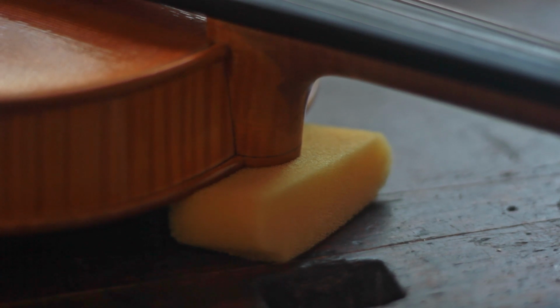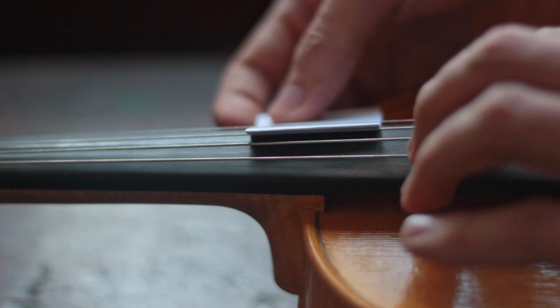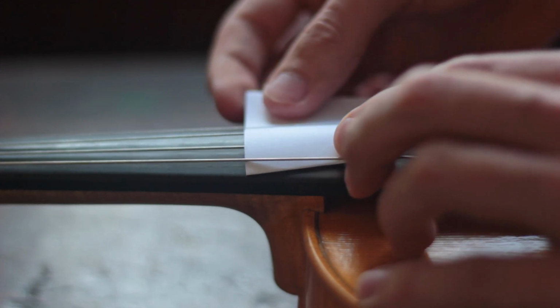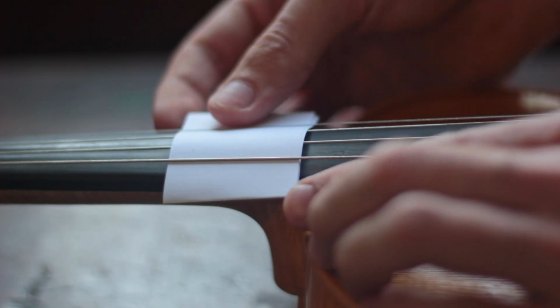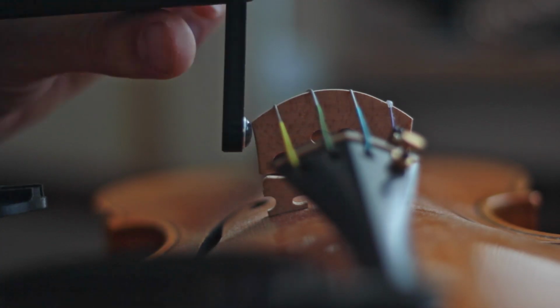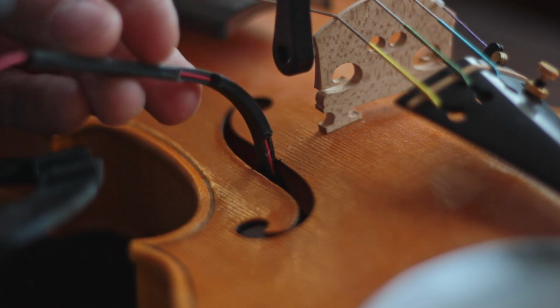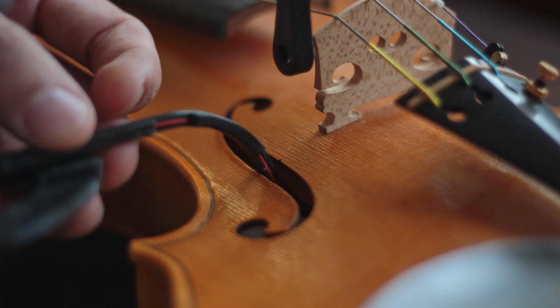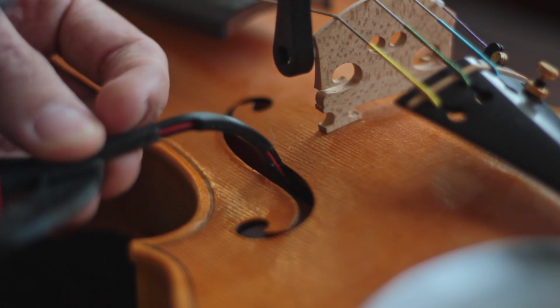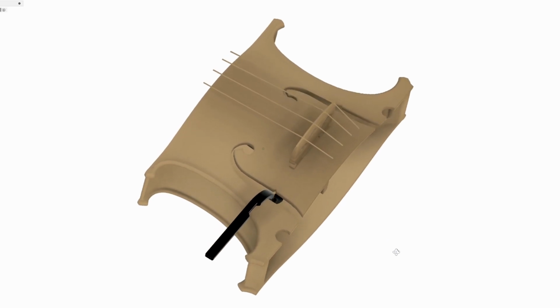Test that the instrument is freely supported by tapping on the neck and observing its vibration. For the measurements discussed today, we will dampen the strings. Here I have prepared a piece of paper to wedge between the strings. You can also use light foam blocks. Now bring the hammer into position as shown earlier. Then insert the microphone through the bass side F-hole. For this you will have to remove it from the microphone holder and carefully thread it through. Here's a cross-section through the instrument that shows you how it should sit.